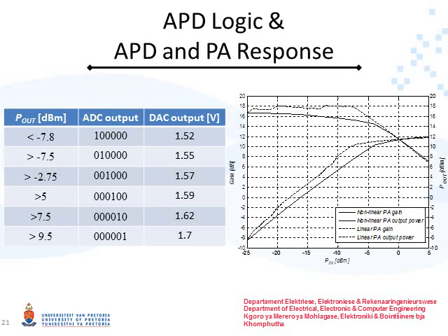Increased gain and linear output power of the power amplifier are achieved when APD is applied to the power amplifier. The gain of the linear power amplifier is fixed around 18 dB, resulting in an increased input power 1 dB compression point of -6 dBm and improved linear output power. The linear power amplifier shows an improvement of 2.5 dBm, at which point no further linearization can be applied and the linear power amplifier begins to saturate.